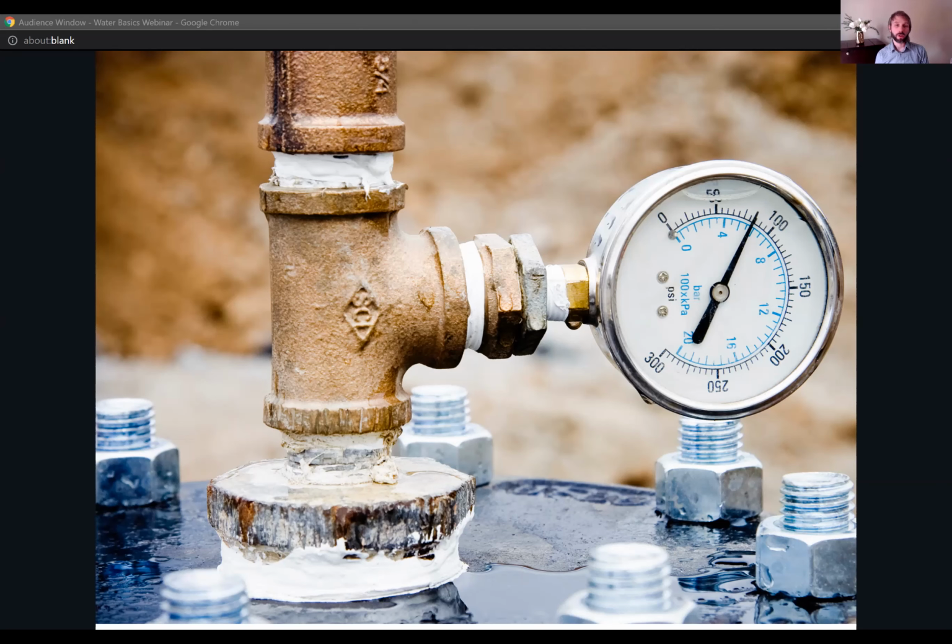On a new construction, we're looking for the plumber to do something called the line pressure blowout. They should always be doing that, and then signing off on a document or recording their results on what they're seeing, to make sure when they're walking away from a project, there's not a leak on a new construction. So we really want to see 50 to 60 PSI as our target pressure area.